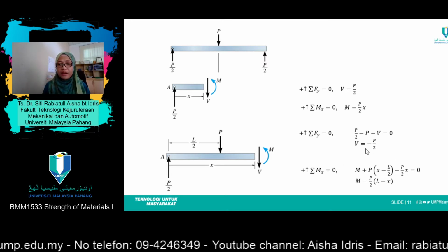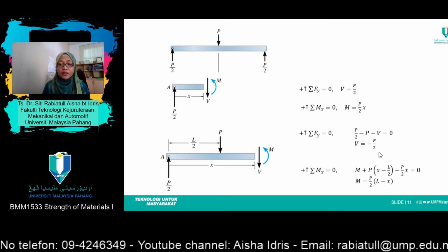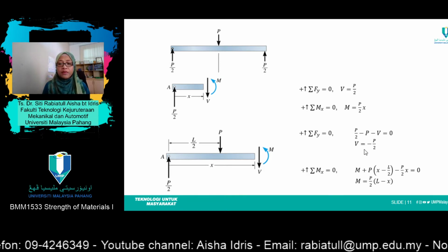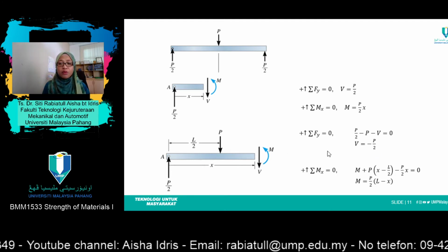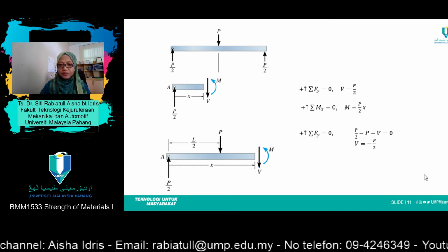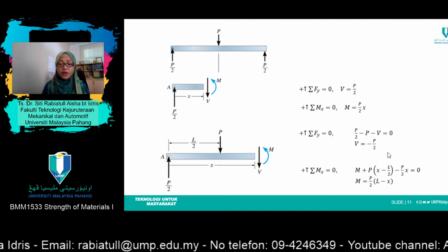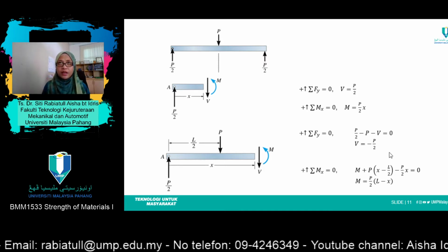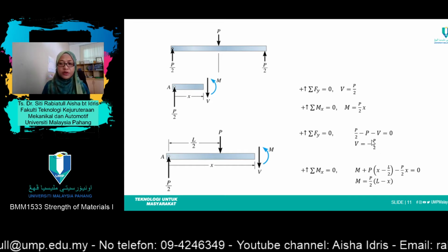For shear force, when X equals 0, V equals negative P over 2, and when X equals L, V equals negative P over 2.